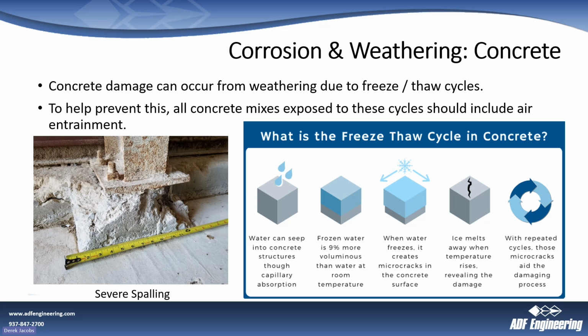and you end up getting large chunks of concrete breaking out. You can see here we have some severe spalling due to the freeze thaw that's happened. A lot of times to prevent this, if we know that a concrete mix is going to be used outside, we'll include air entrainment, which is almost like a detergent, like soapy bubbles. That'll put air pockets in the concrete, which doesn't affect the strength that much, but does allow for voids for the water to expand into when it freezes. So that's kind of a prescriptive method.